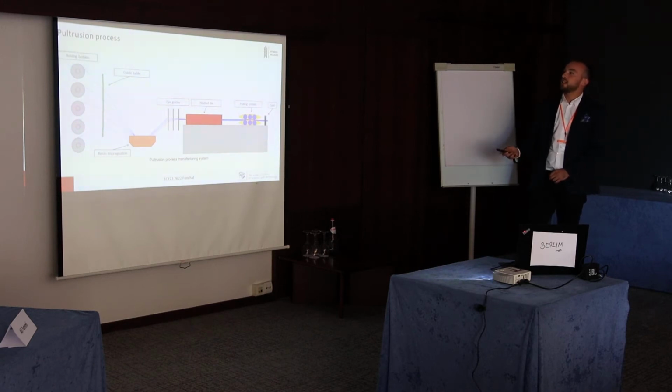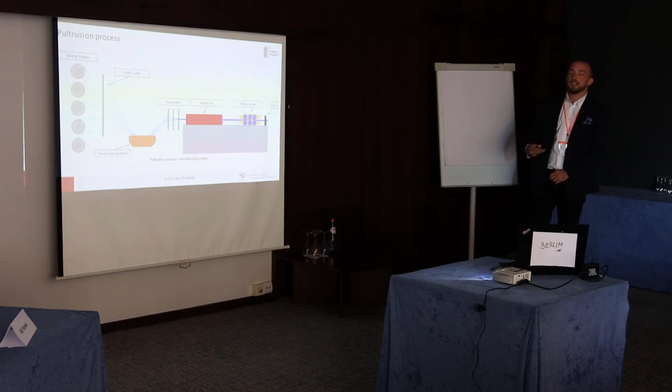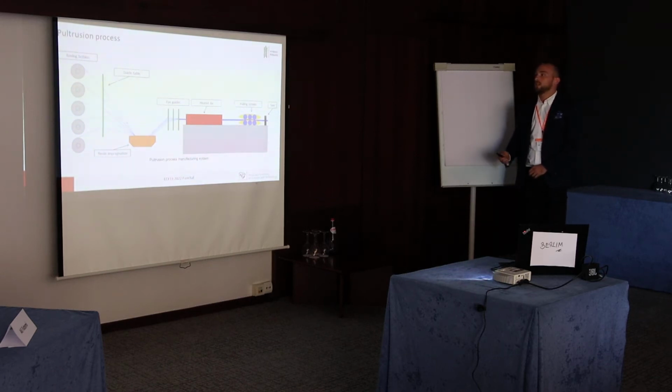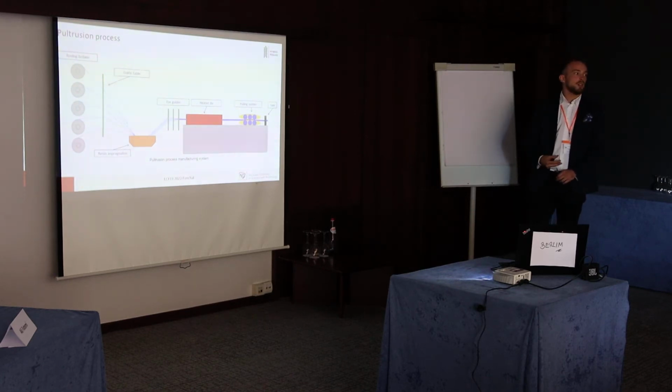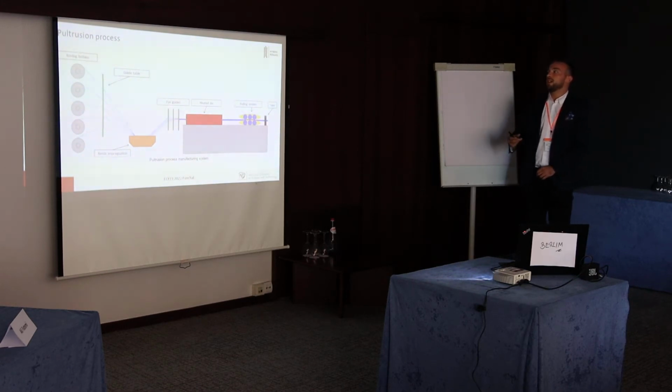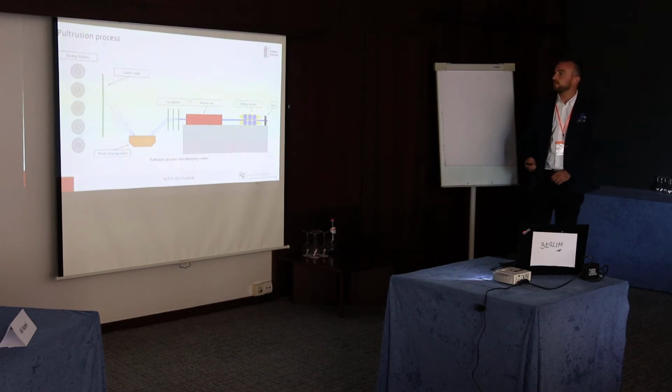In the heated die, our fibers are cured, and in the end we have the solid profile. The continuous movement of the system is provided by the pulling system, and in the end we have the saw machine which cuts our profile to the specific dimension.